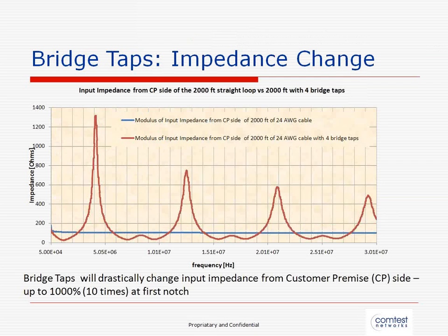The impedance seen by the modem is very important. For example, if the modem is designed for a 100 ohm system, the impedance of the cable should remain 100 ohms to avoid error-producing reflections and losses. At high line rates, such as those in VDSL2, these signals can be distorted if the impedance seen by the modem varies. The blue trace is the impedance when the modem is connected to a POTS splitter at the entry point. You can see that it observes a fairly steady 100 ohm impedance.